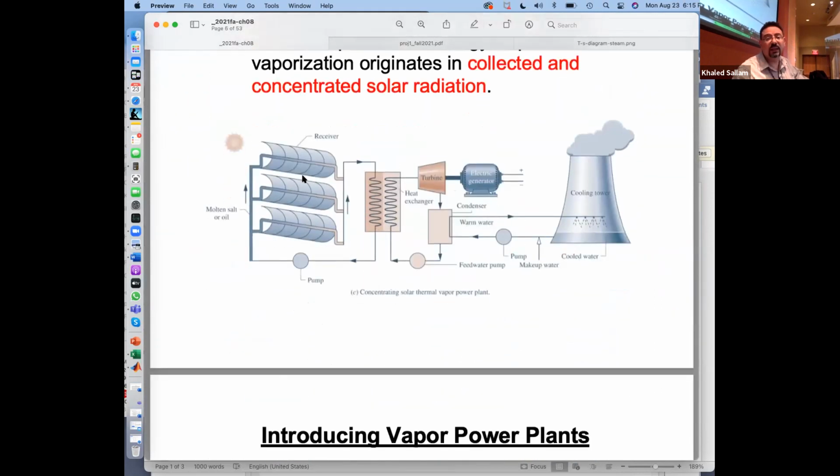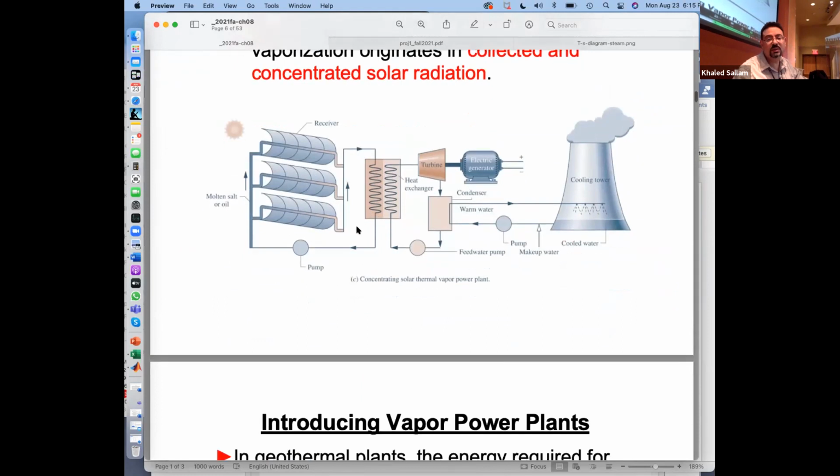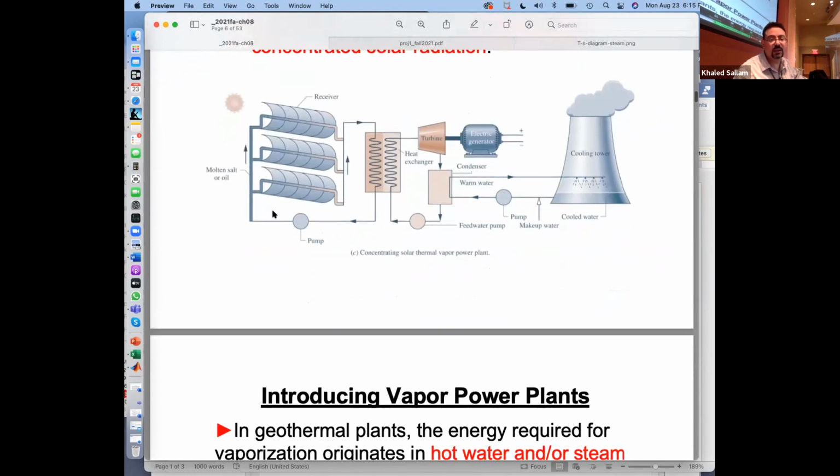Very good. And again, he's saying, well, you can also do it with solar thermal. So just make the sun heat the working fluid over here. That working fluid could have antifreeze so that it wouldn't solidify in the winter, or could have small nanoparticles. They call them nanofluid. Why would you add nanoparticles in your liquid? To make the conductivity go up, because it behaves as if it's metal. So very high conductivity, absorbs the heat very quickly, right?